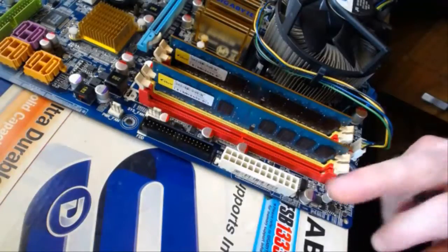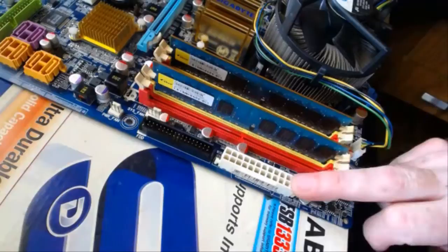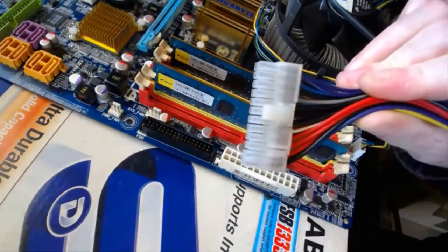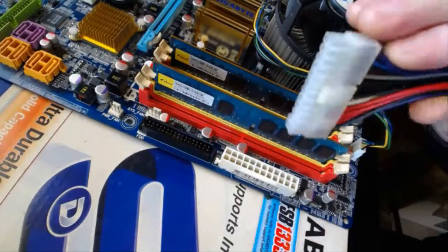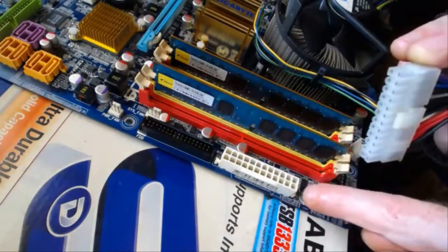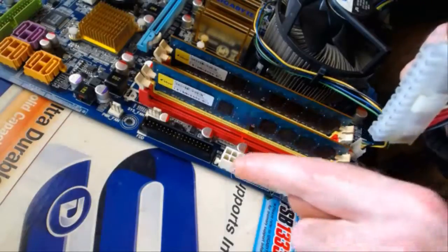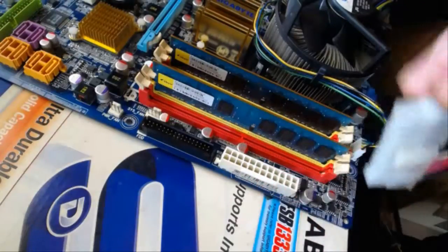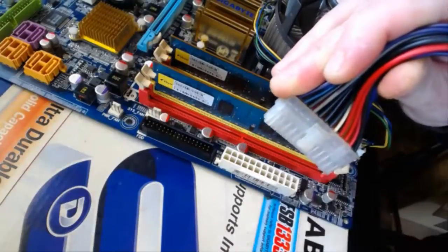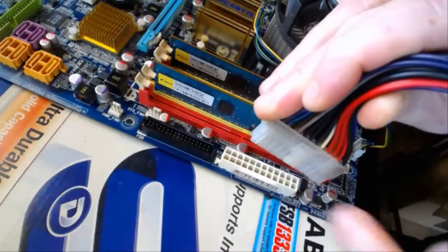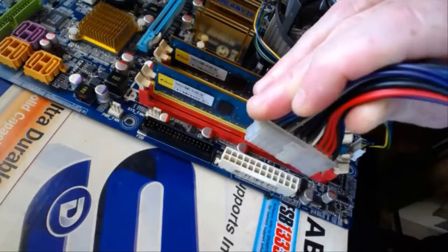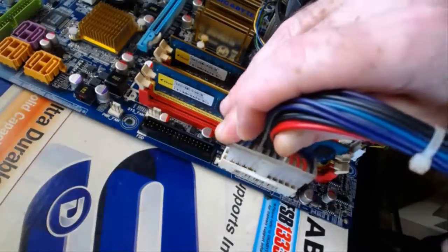Now, this is the 24-pin connector for your power for the system's board, and this is the 24-pin connection that is made to that connector, and it's keyed. So all these little guys here along, you see there's different shapes there, so some of them are beveled and some of them are square. So you'll see a little edge on the side of the 24-pin connector, and that corresponds to this little clip that's on the side of the connector.